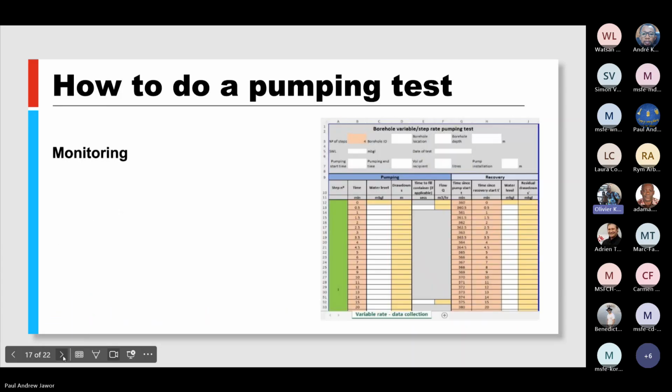Thank you. So after having carried out all of the pump tests, or while carrying them out, as I mentioned a while ago, it's very important to collect the data, and we have these sheets which help us to collect the drawdown level in the field. Generally, we can plot this information directly on graph paper in the field for those who are experienced and comfortable with it. We can actually finalize our pump test and even get our safe yield while in the field.